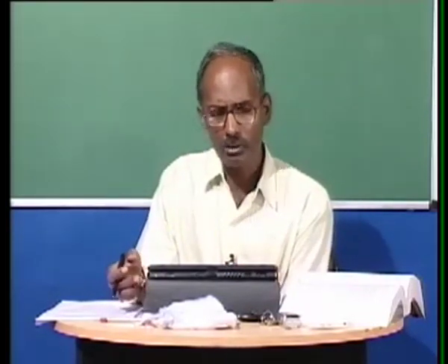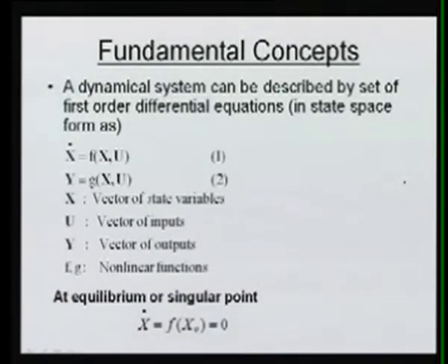To understand how we have simulated these studies, let us go through certain mathematical background, which means we have to write the dynamic system behavior in terms of differential equations. A dynamical system can be described by a set of first order differential equations in state space form. Here this is equation 1, and here is equation 2. X is the state, the vector of state variables, whereas u is a vector of inputs, y is a vector of outputs, and f and g are nonlinear functions.